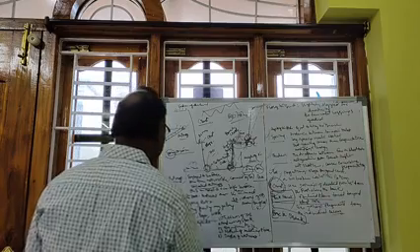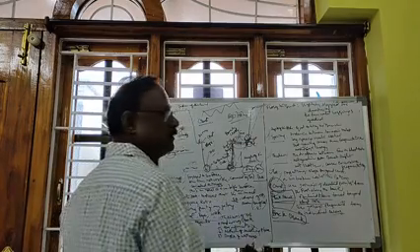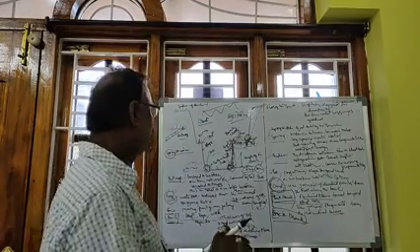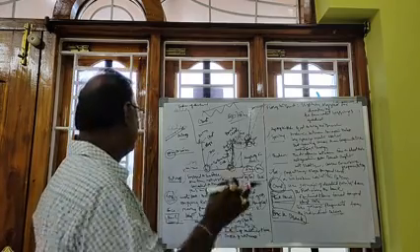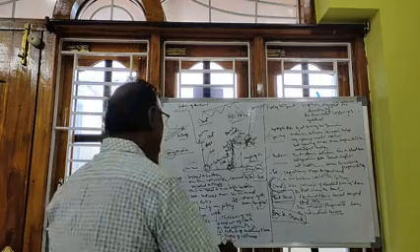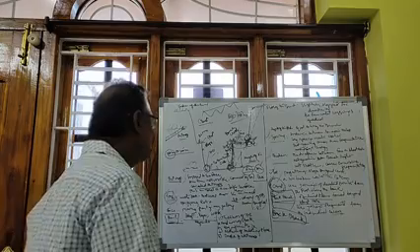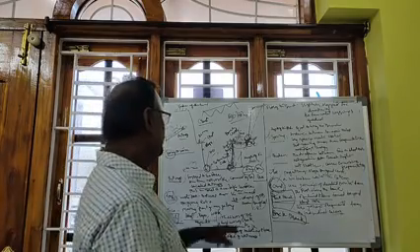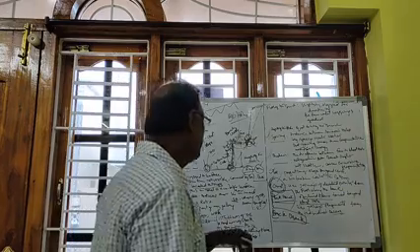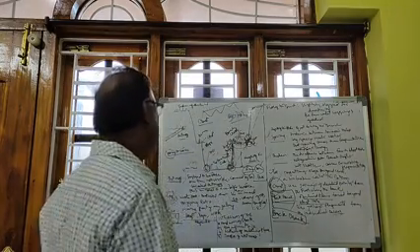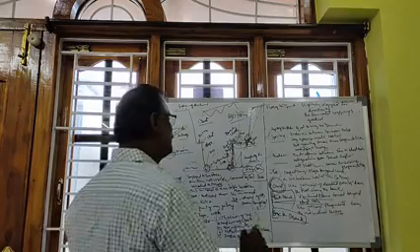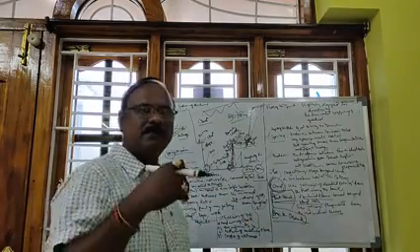And finally, the bench parameters. The height of the bench depends upon five parameters: the thickness of the overburden, the hardness of the strata, the equipment size, the nature of the bedding layer, and the degree of wetness. So these five parameters decide the bench height.